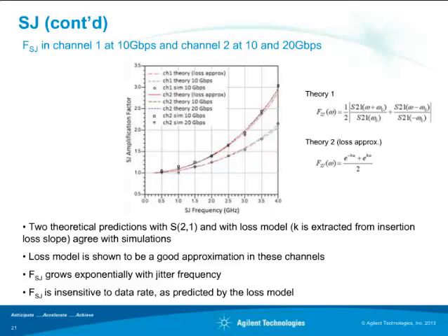I assume it meant the data rate, but I could be wrong. Well, as a matter of fact, this analysis applies to both high frequency and low frequency, because there's nowhere we assume the frequency is high or low. The reason it takes off at high frequency is because that's where the loss kicks in. It just depends on the loss versus frequency. So it's really the shape of the curve versus the frequency you're working at.